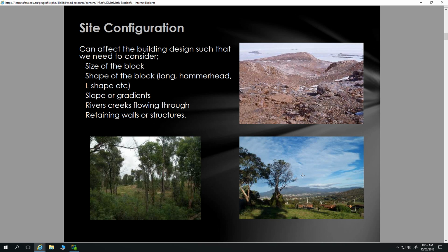Because the risk we run with a scenario like that with the fill is of course the subsidence and the settling and collapse of that portion there. Yes, we can auger through here, put in some piers and lock into that stable ground.